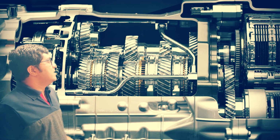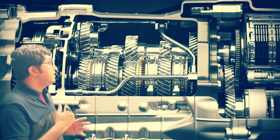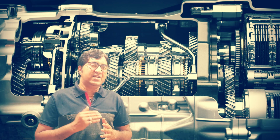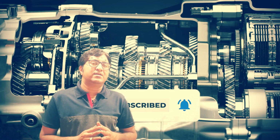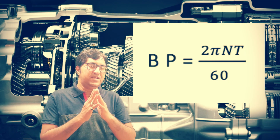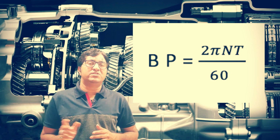The function of the gearbox is to reduce or increase the speed whenever required, and it also changes the torque. For example, in first gear the speed of the vehicle is slow, so the torque is higher, because we know the equation for power: brake power equals 2 pi N T upon 60.